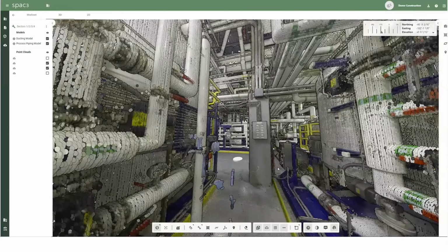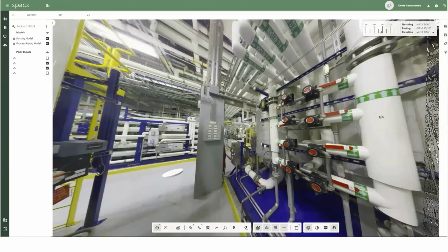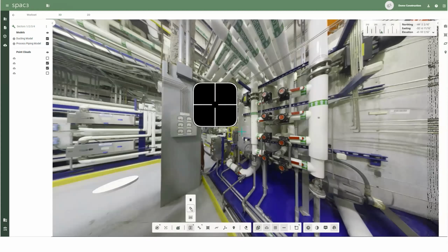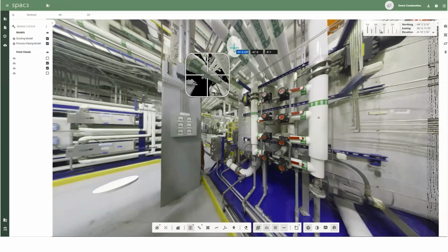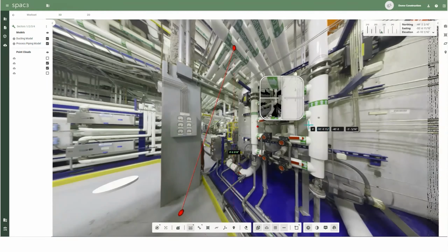In addition to the variance report, the other part I like to use Solidspace is all the information and models are hosted on their web-based platform. Anyone in the project team can easily access the information and the models. For people that work remotely on a project or don't have software like Revit or Navisworks installed on their computer, or simply not used to navigate the model, this is a huge benefit for them to view the site, take a measurement, overlay the point cloud and the BIM model to understand what's in the field and what's being designed.